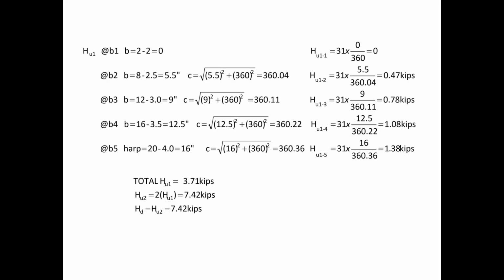Generally, that is correct. I have seen tensioning setups where the strand came into the abutment at an angle, and then there was a stressing plate that was at an angle so that the strands were actually tensioned. The jack was at an angle, tensioning the strand as opposed to being horizontal. So I have seen that done. That is very unusual. Most of the time, you are correct. There would be a hold up near the end of the bed so that the strand is horizontal at the chuck.